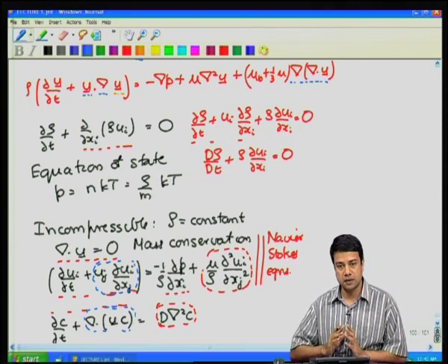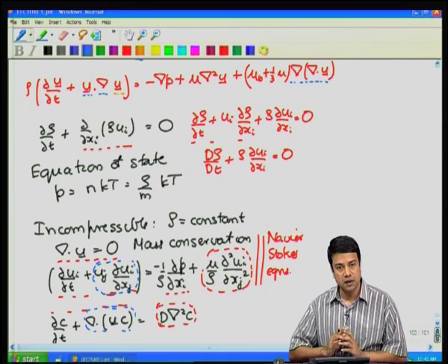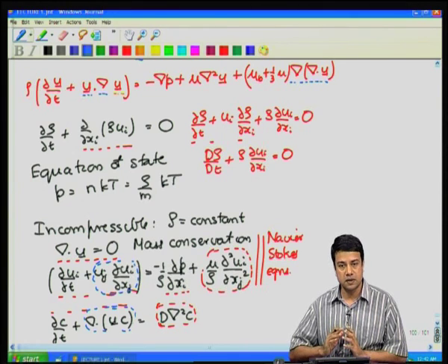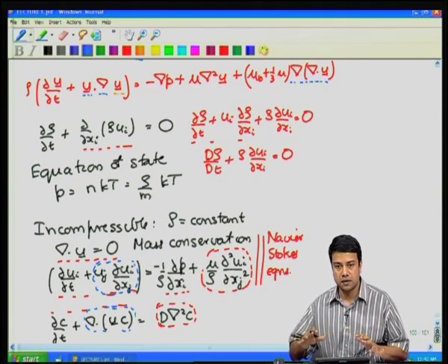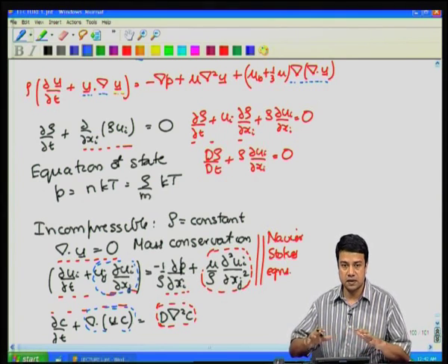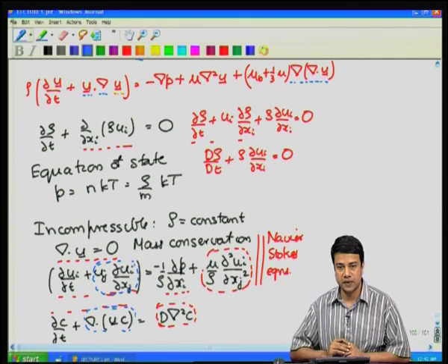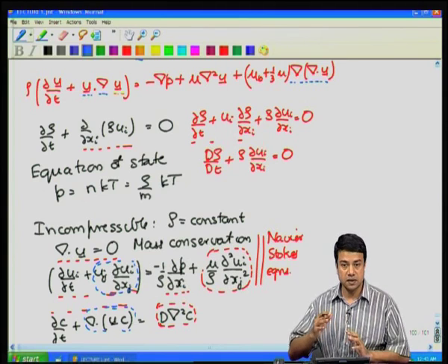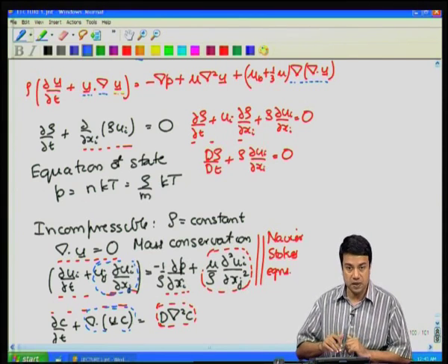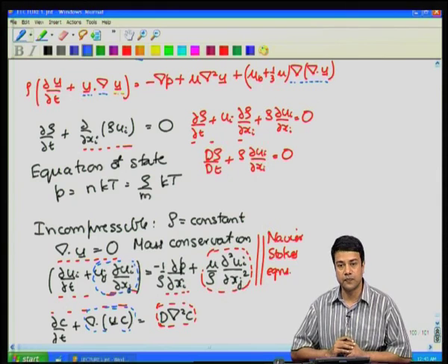For a nonlinear equation, it is no longer so. Because of this, the Navier-Stokes equations, mass and momentum conservation, are considerably more difficult to solve than the concentration equation. In the concentration equation, if you have a certain concentration field which satisfies the mass conservation equation, if I multiply the concentration by a factor of 2 at every point, it still satisfies the concentration equation.